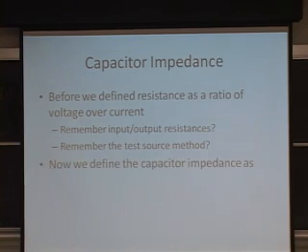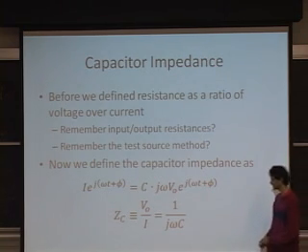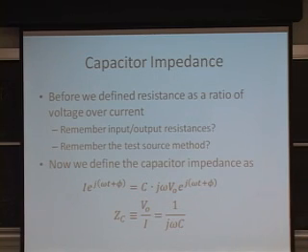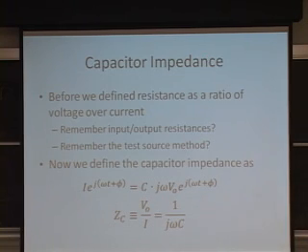So if we do the same thing for a capacitor, we cancel, again, the exponentials on each side, and we see what your book takes as the capacitor impedance. It's 1 over j omega C. This is where it comes from. It comes from just taking the AC assumption and plugging it into your IV relations. So that's how you get the ratio of voltage over current in this case.